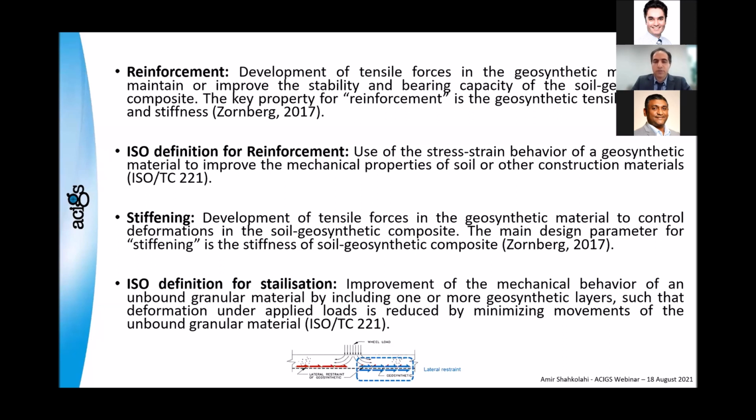And stiffening, according to Dr. Zornberg, is development of tensile forces in the geosynthetic material to control deformations in the soil geosynthetic composite. The main design parameter here is soil geosynthetic composite stiffness. And according to ISO, stabilization is improvement of the mechanical behavior of an unbound granular material by including one or more geosynthetic layers, such that deformation under applied loads is reduced by minimizing movements of the unbound granular material.